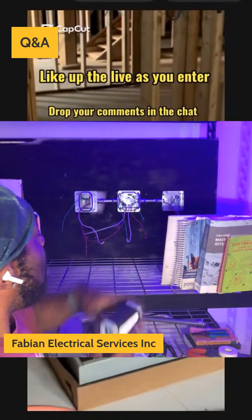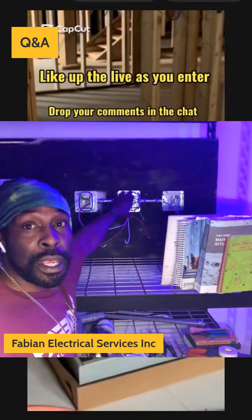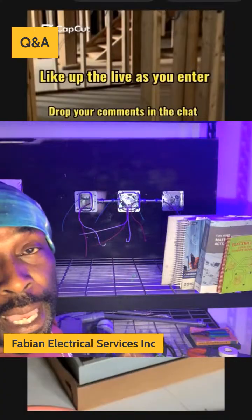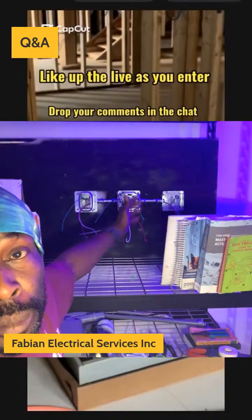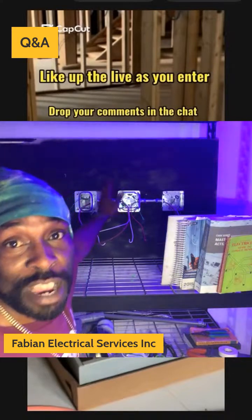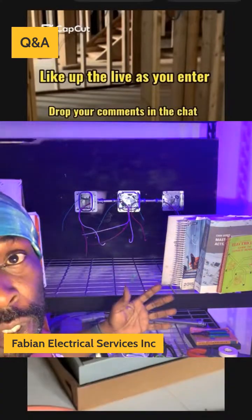As you can see, I have these wires coming out of here. These are number 12 gauge wire, and I have here my 2-gang plaster ring, it's called. So in order for us to obtain our box fill, or if there's a cluster in here, and to pass your code, you simply have to use one of these extension rings. Once you use the extension ring, you are 100% safe passing your inspection.